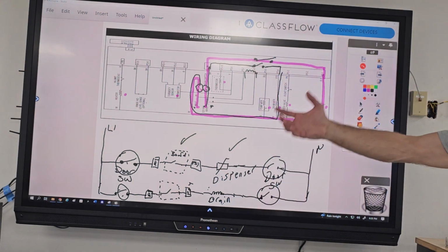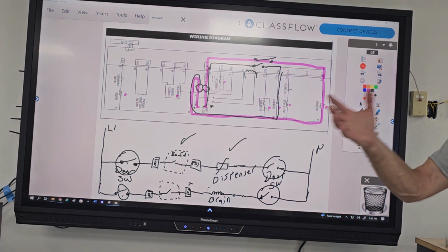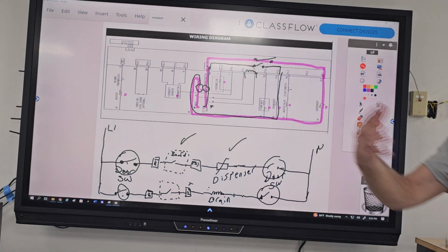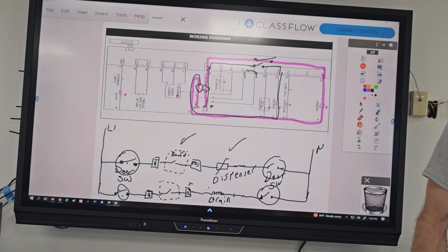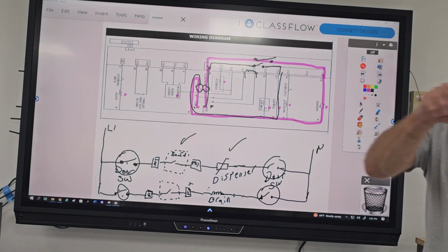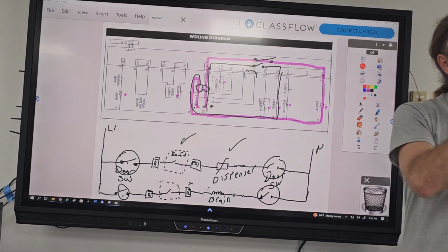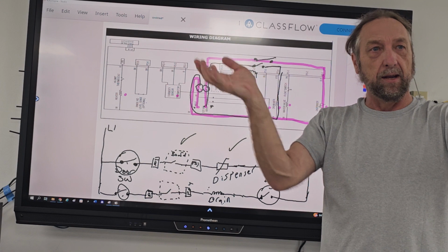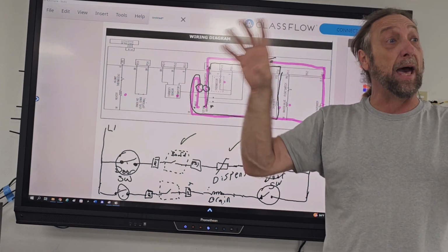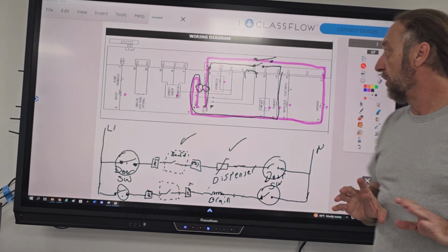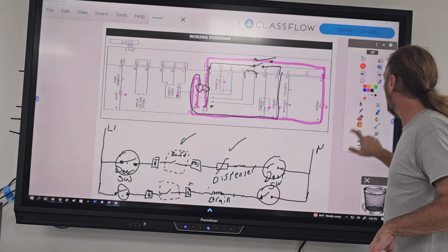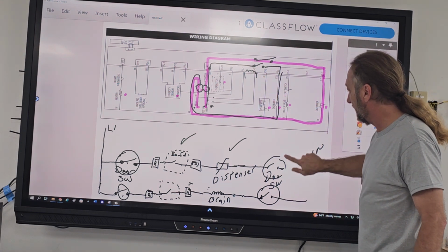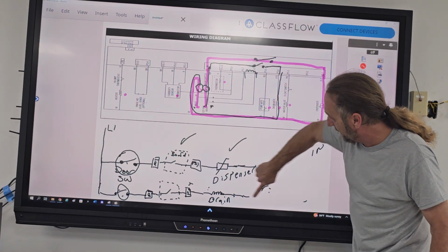So I went from 4 possible parts that could be wrong, narrowed down just by looking at what's working and what's not working. If I try to figure out why something's not working, I look at its circuit. I look at another part that's working and ask, do they share some parts? If they do, the parts that they share have to be good. So what I do is I take my eraser here, and I just erase all this up to this point now.